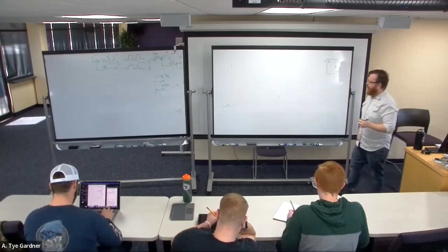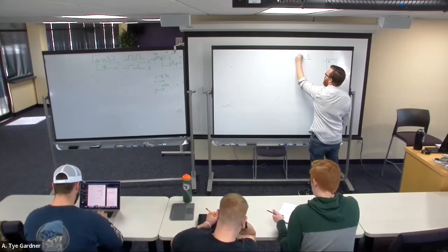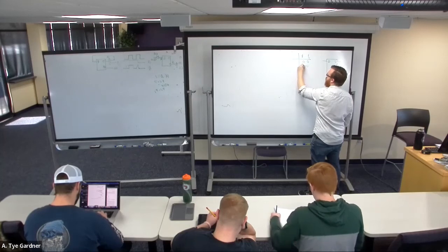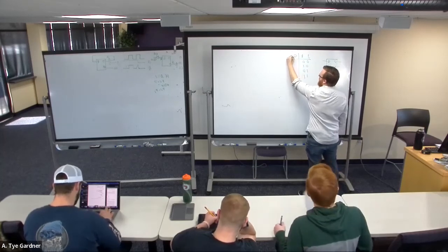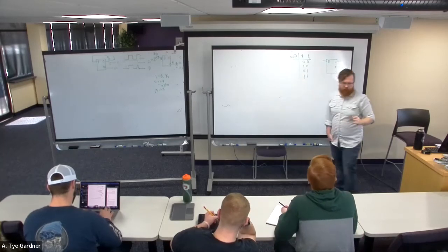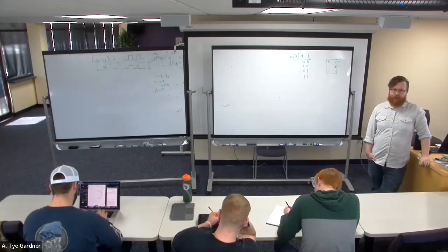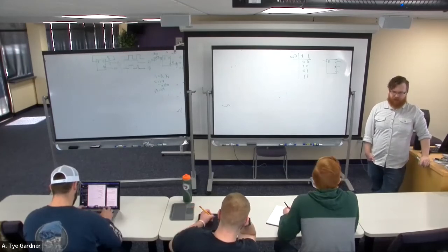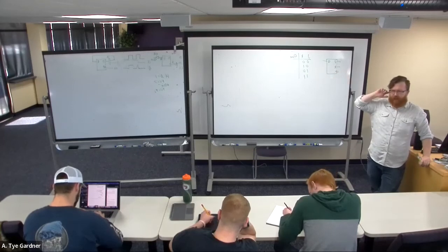And what the JK does is the following, where I have inputs JK, and this is going to be the next Q. And in this case, the n+1 is the number of clocks, right? This is really where this notation comes from, which is discrete mathematics, which is the next Q, the next time there's a rising edge of clock.